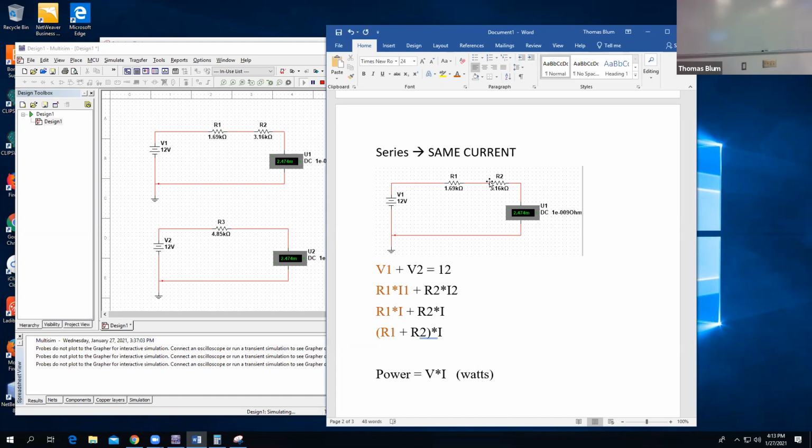And less heat, right? Say again? Less heat. Strictly speaking, heat per second. It's a matter of power. So overall, I guess individually they'll generate heat, but it's more about power. So it's more like heat per second. But yeah, they'll each be generating less heat. They'll have smaller wattages. So that's a reason why you might not want the equivalent. You might want the original 2 resistors. But in terms of volts giving currents, they're the same, but there are reasons like power considerations where they're different.